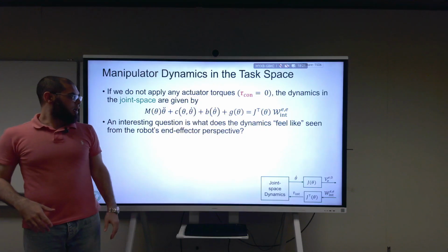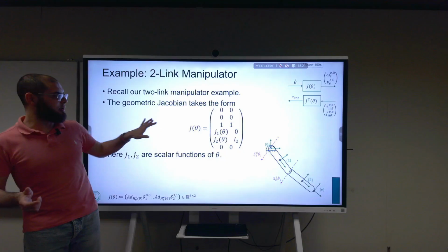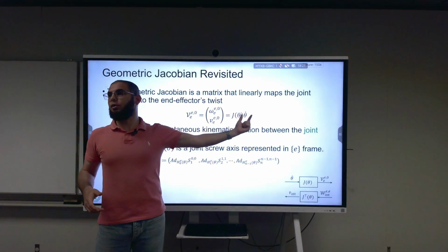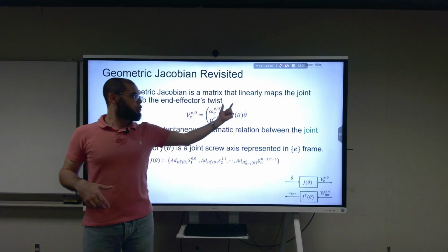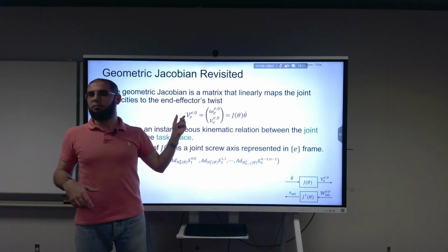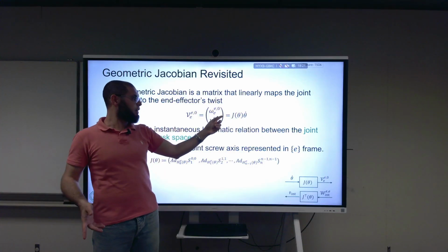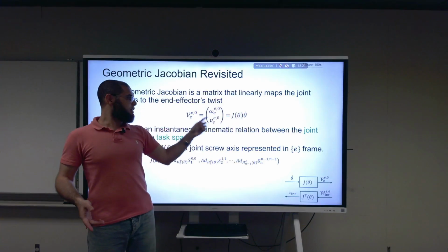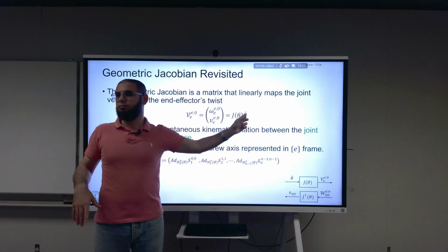Also, theta dot itself, if you go back to this equation, I can replace by J inverse multiplied by the twist. And if I want J double dot, I would differentiate that equation. So V dot will appear multiplied by J inverse, plus V multiplied by J inverse dot. You agree?